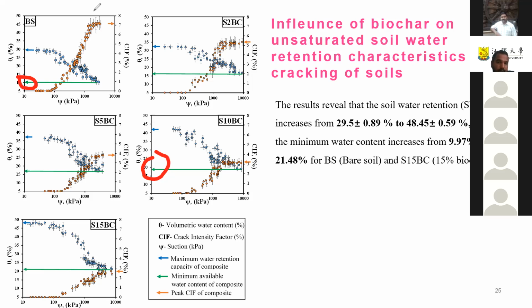So we do not have to worry about the aging effects of biochar here, unlike, I think, natural fibers. You might have read in the literature that natural fibers are vulnerable to decomposition over a long time, but biochar is not. Biochar can remain stable for over 100 years. The fibers are prone to decomposition by microbial activity, but biochar has already been thermally decomposed from biomass, so it remains more or less stable for more than 100 years. That's why, in terms of life period for engineers, this material can sustain its efficiency for a long time.